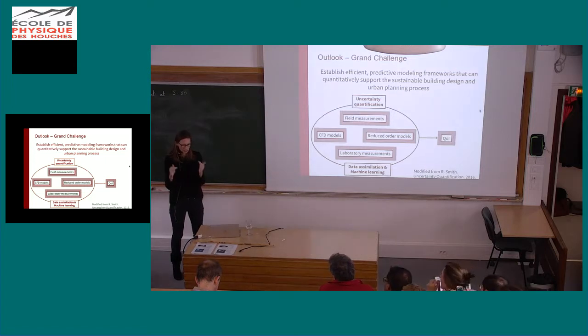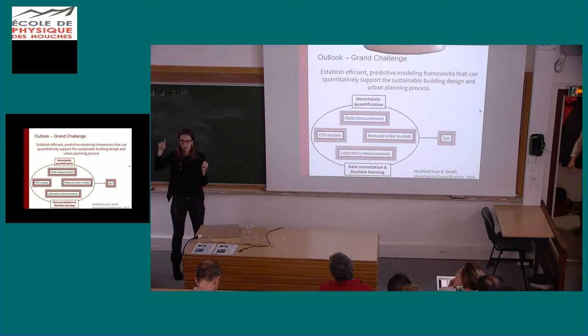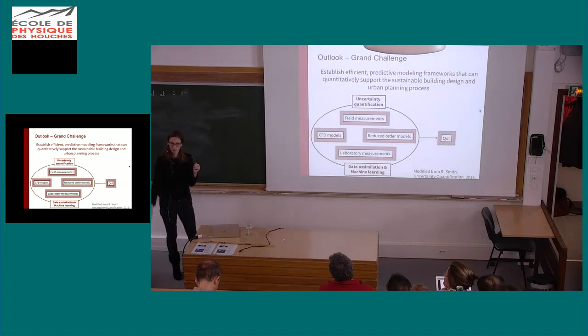For Stanford, what we did is we initially ran CFD simulations and we tested our data assimilation method. And we looked at the errors that we get depending on where in the flow our sensors are. What you see is that definitely you need a sensor on the rooftop, which is totally obvious because that's going to correlate most with the inflow wind direction. But then additionally, you probably want a sensor at pedestrian level as well, because that's going to give you some information about the vertical variation. You do not want to put it in a street canyon where the flow is predominantly going to go in one direction, because that's not going to help you infer much. The problem will be ill-posed. So yes, we used CFD simulations to try and understand where to put them.